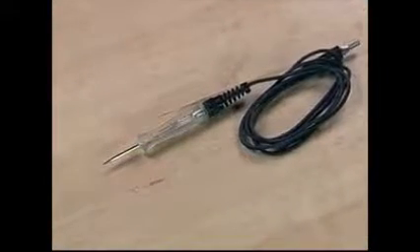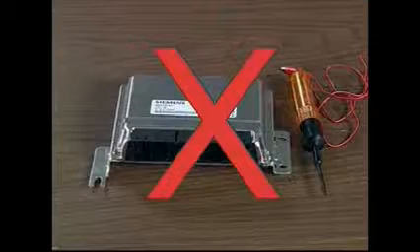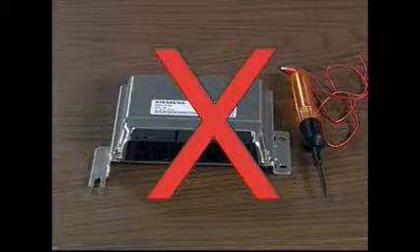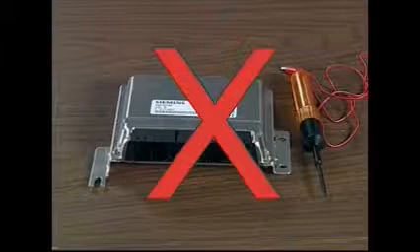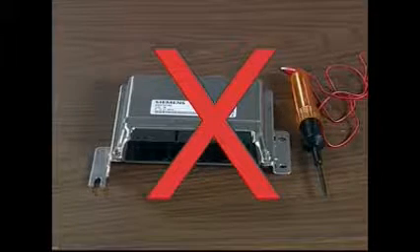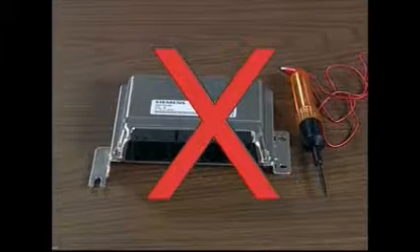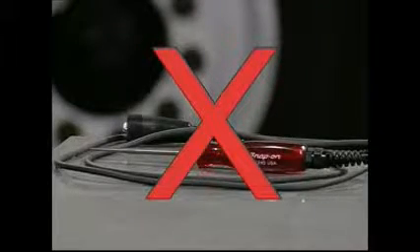Test lamps are an easy way to test a circuit for the presence of current. A big word of caution before we look at the tests you can do with a test lamp. Never, and we mean never, use a test light on any part of a circuit that leads to an electronic control unit or on a supplemental restraint system airbag. Self-powered test lamps send an electrical current through the circuit that can cause the sensitive circuits in an electronic control unit to melt, or they can cause airbags to deploy.